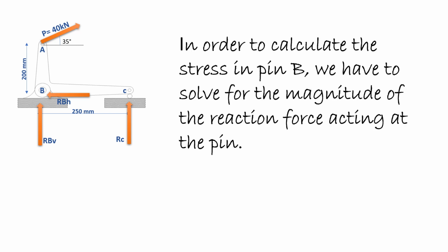So in order to calculate the stress in pin B, we have to solve for the magnitude of the reaction force acting at the pin B. Since we are given the diameter of the pin, and we have this vertical and horizontal component of force RB, we can get its resultant, and we will use that resultant in order to get the stress in the pin B.